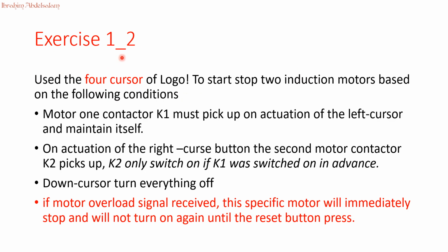Exercise 1_2. The motor's overload signal is considered. So if a motor overload signal is received, this specific motor will immediately stop and will not turn on again until the reset button is pressed.